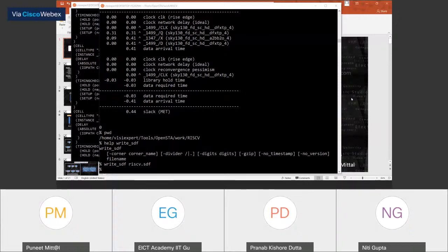If you remember, in one of the slides I mentioned the Elmore delay model. That particular day, I said you can read those slides. So the tool considers those Elmore delay models and calculates the RC delay value of a wire. Yes, so SDF just masks the value from the .lib file.